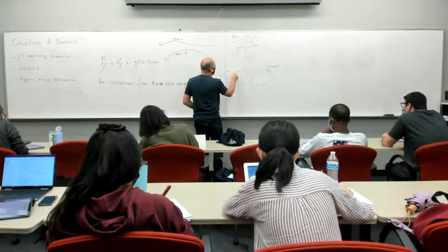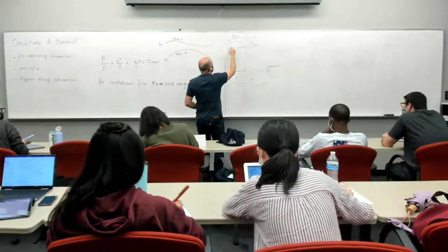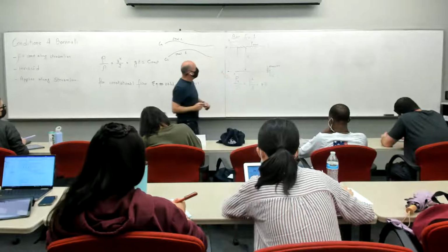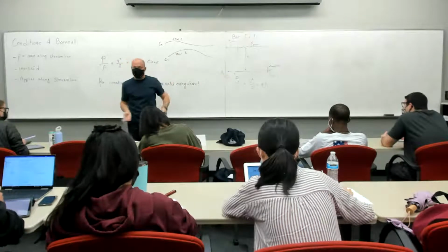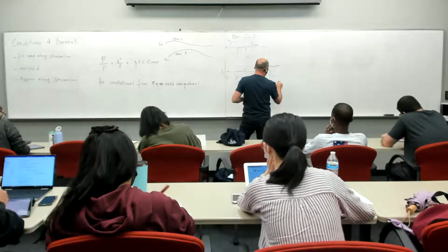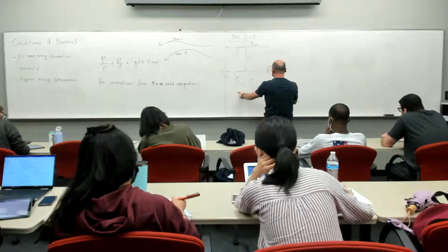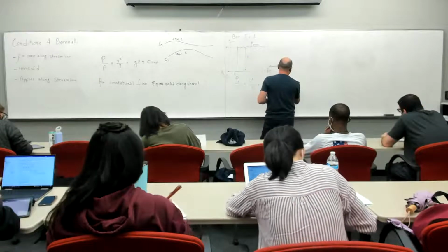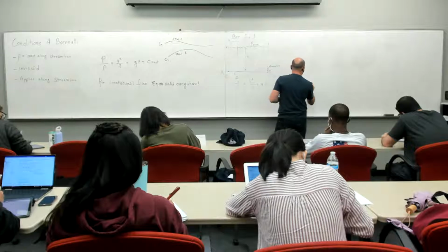So we say this is X, for example, and this is Z. So this would be Z1, and this over here would be Z2, or 0. Doesn't matter, because what matters is going to be the difference. So that's at point 1, equal to pressure at point 2, assuming density is the same along the streamline, plus V2 squared over 2 plus gZ2.